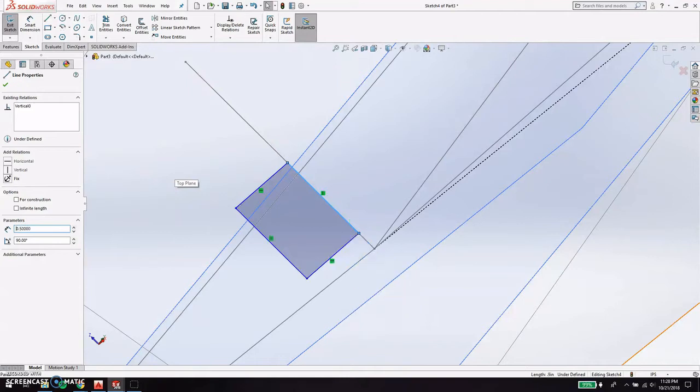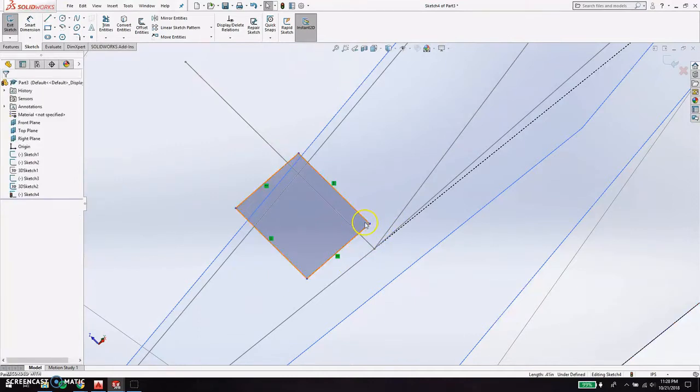This is 0.5. And this right here is 0.5. Let's just make sure that this, yeah, so see how it went in the wrong direction? The way that you can fix that is by assigning some little restraints.